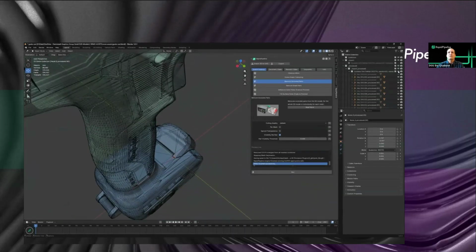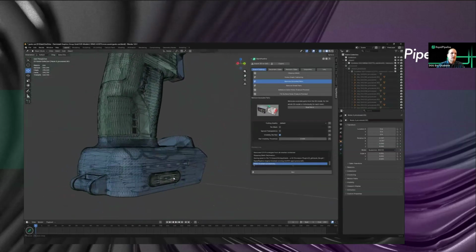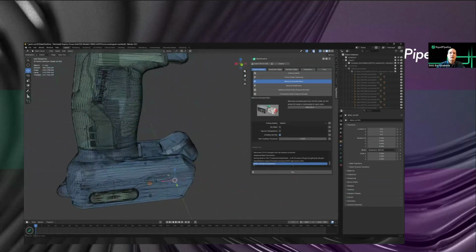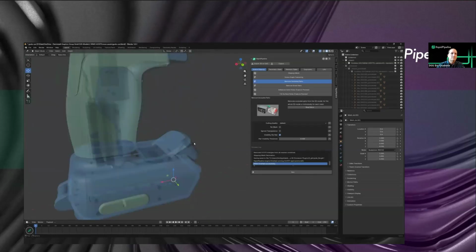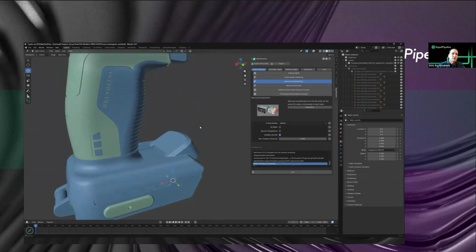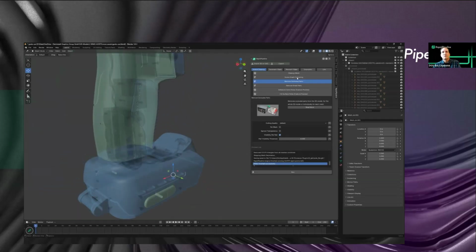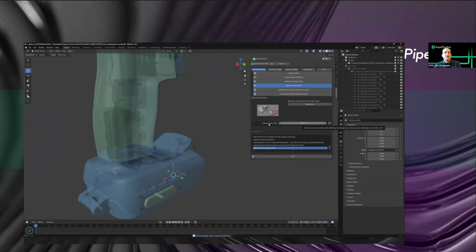The other option here as well is if we look at the original here, we can just cull the small parts. So we have all these little screws here, which are really hidden inside the model. You can't really see them from the outside, but they are there, right? In X-ray, you can really see them. But say you just want to cull away the small parts, that's easy as well. There's a remove small parts function, and it basically looks at anything in scene units, which generally is 1 meter. So here it's saying anything that's smaller than 1 centimeter, go ahead and remove it.